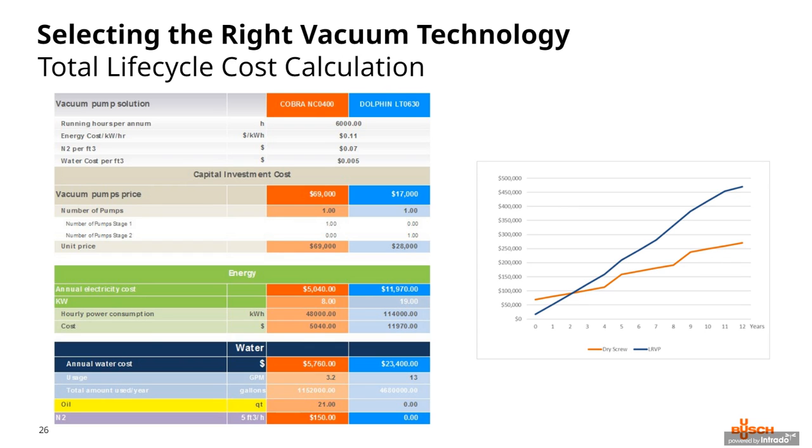Now the dry screw pump does require a small amount of nitrogen for the discharge side seal, and that essentially trickles in at around 5 standard cubic feet per hour in this case. But that amount's relatively inexpensive compared to the cost of the rest of the system. The seal purge isn't a necessary option if you choose a lip seal version, but for most applications involving chemicals and most applications in the pharmaceutical industry, we're going to have mechanical seals, which include a necessary discharge side seal purge.